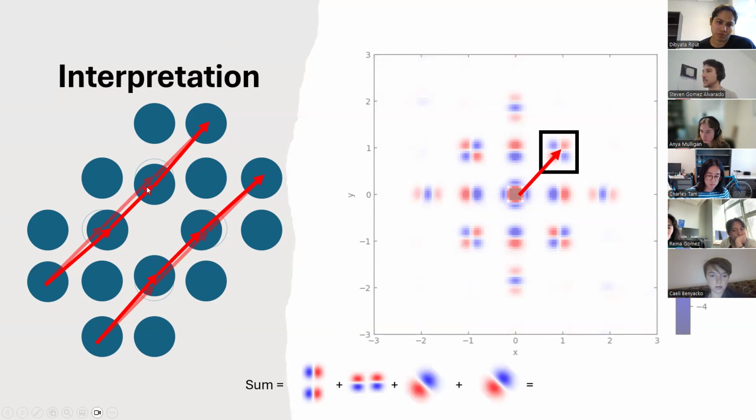And then the last one is these contractions, right? These two atoms, as they collapse towards the vacancy, if you think about standing on one atom, it effectively feels the other atom moving closer to it along the diagonal direction, even though one is moving to the right and one is moving downward. From each other's perspective, they just see each other getting close. Okay, so that's going to impart some contraction along that direction. So if I add up all these, I get that four-leaf clover looking thing. Okay.